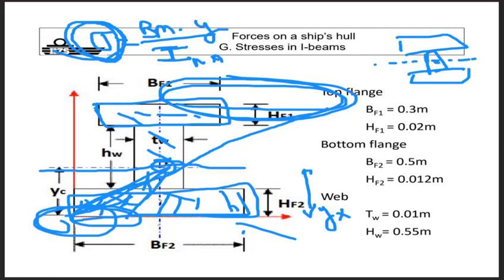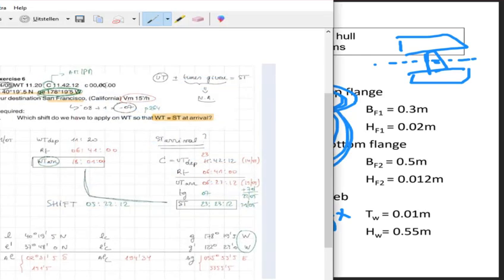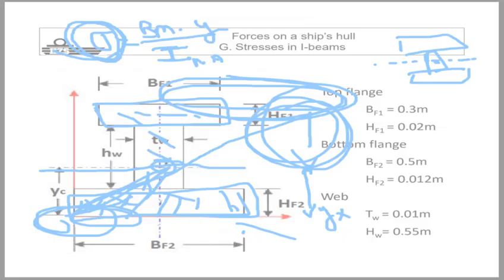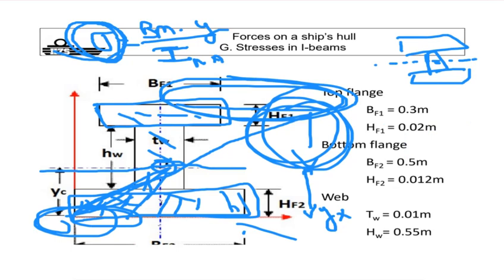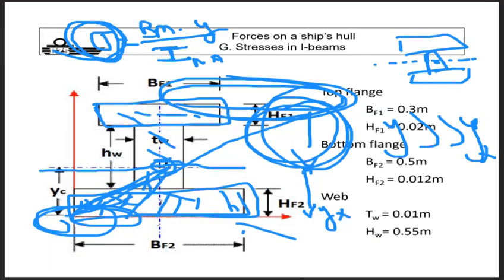And as your neutral axis is lower than mid-height of your profile in general of a vessel, the distance you have to take into account to come to the worst case stresses on that spot will be, of course, this end, this part. And that is much bigger. So this y is bigger than yx. So you always have to check where your neutral axis is located.